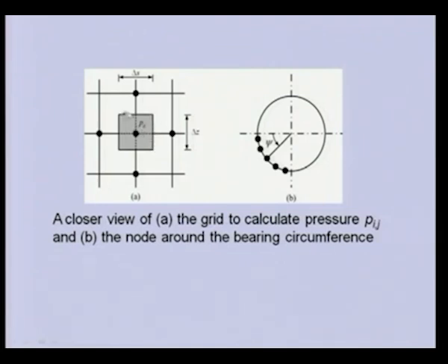This gives the force which the fluid exerts in the radial direction. This is the way we obtain the force value from pressure, and then we can take the components of these forces in different directions, horizontal and vertical, and see their force balance.